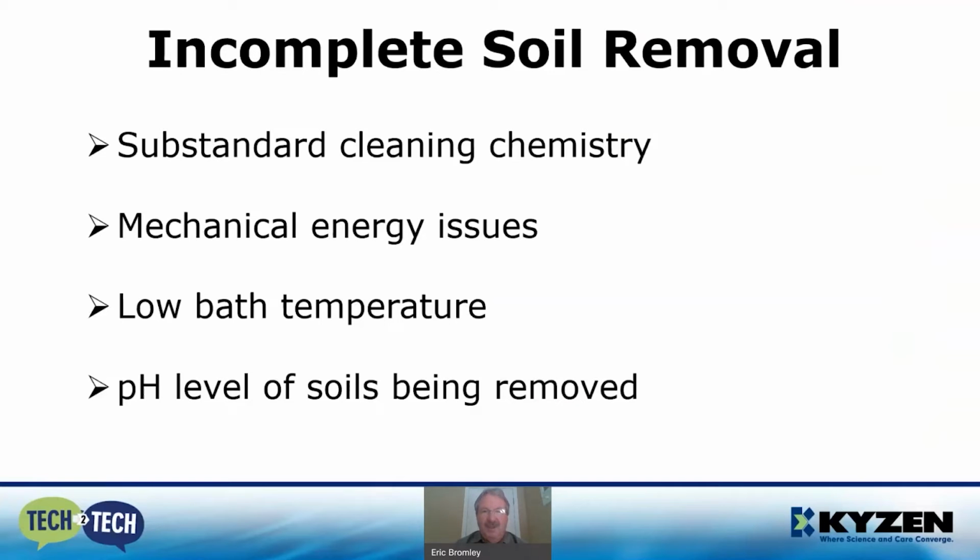If it's a cabinet spray washer, maybe the nozzles are not working up to their full potential, or they're misaligned. If it's an immersion process, the spray under immersion pumping, the pumps may not be working correctly, or the filters could be partly plugged. If you're using ultrasonics, some of the transducers could have failed or just not be aligned correctly, so you're not getting the full benefits of the cleaning process, and in the end that will cause some streaking and spotting.